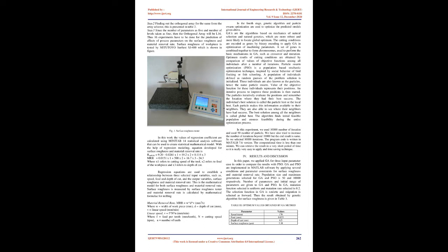In the first stage, face milling operation is selected for study. In the operation of face milling, the axis of the milling cutter remains perpendicular to the surface being milled. Cutting action is done by cutting edges of both sides, end and outside periphery of the milling cutter. 3 input variables are selected, as these variables are proved to have significant influence on the output measures such as surface roughness. Surface roughness and material removal rate are the output measures for our case.